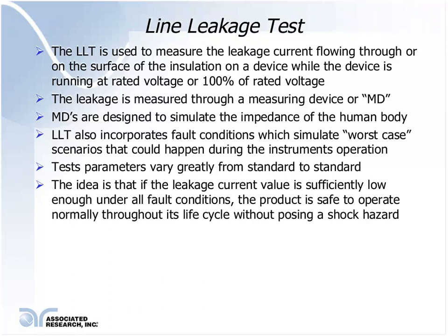However, the line leakage test differs in that this measurement is performed while the product is running at the rated voltage, or at a high line condition of 110% of rated voltage. This is specified by some medical safety standards by UL, like 60601-1, where line leakage tests should be run at a high line condition.